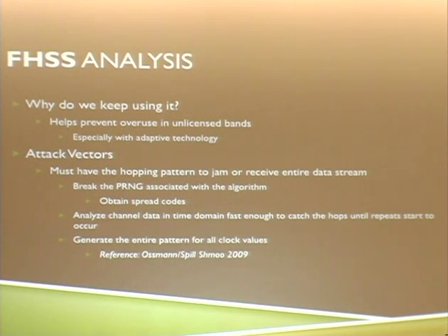Some of the attack vectors. Obviously, you must have the hopping pattern to jam or receive the entire data stream. This was the entire intention when it was created. Hedy Lamarr developed this for military reasons, to prevent the jamming of our radio-controlled torpedoes. So anti-jamming is one of the overall benefits of the technology. Again, there's the always very well-known pseudo-random number generator break. If you realize there's a low amount of entropy, or the not-so-randomness, of the generator that produces the sequences in which you're hopping, that becomes another attack vector.